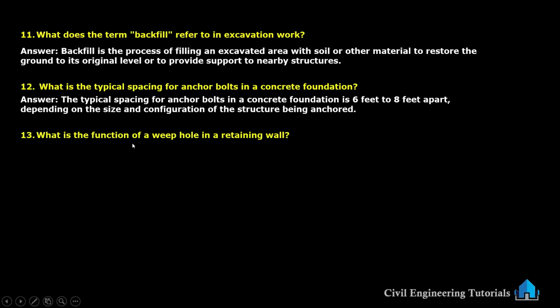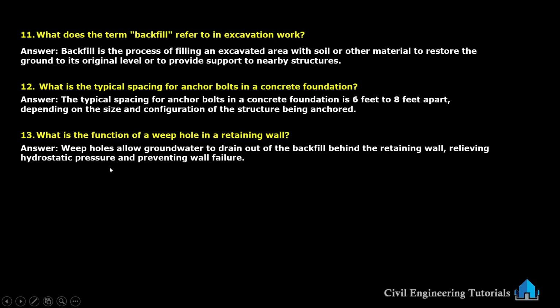What is the function of a weep hole in a retaining wall? Weep holes allow groundwater to drain out of the backfill behind the retaining wall, relieving hydrostatic pressure and preventing wall failure.